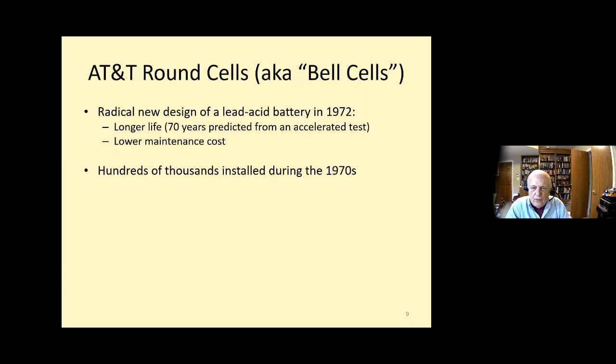Before too long, they had hundreds of thousands in service during the 1970s. However, in 1978, they suddenly discovered that there was a serious unanticipated failure mode where the positive post in the lead acid battery was corroding. They decided they needed a survey to figure out how bad the problem was.